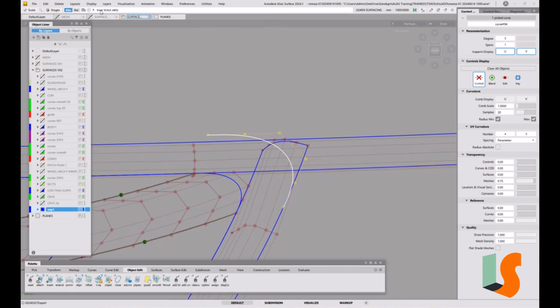I could scale it by hand. Obviously that's a bit time consuming, but I can go up here and put in a scale. So if I press tab, I go into there or click into there. Now it's got absolute on at the minute, and I want it relative. In other words, if I put in absolute and put in 1, it'll go back to the previous size. If I put in absolute of 1.5, it'll be 1.5 times as big as the original.